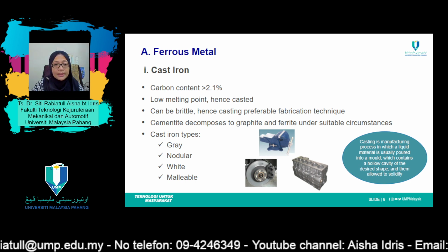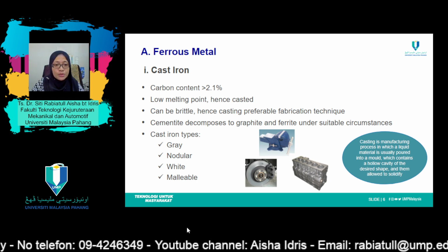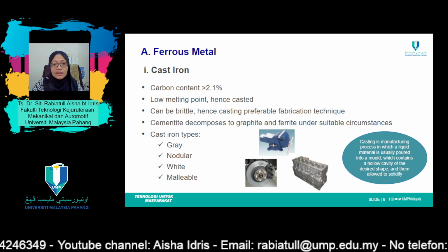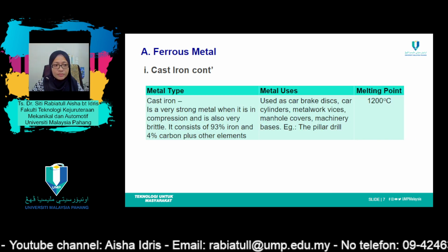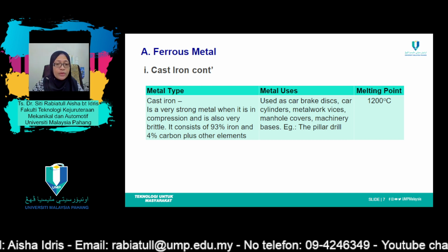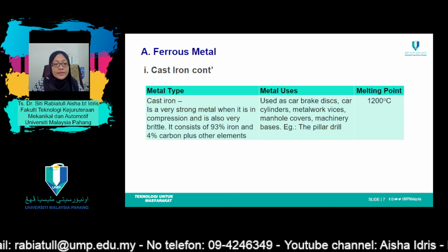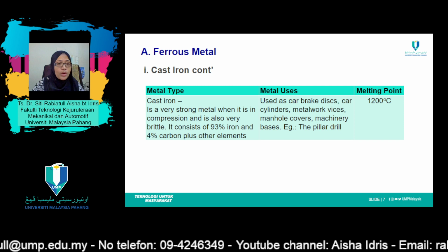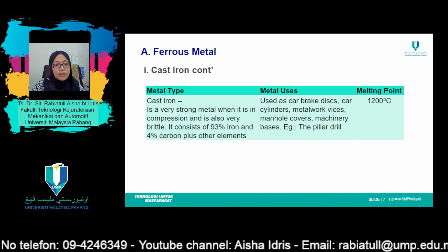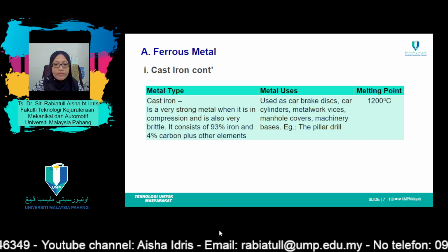And cementite is a metastable compound, and under some circumstances, it can be made to decompose to form alpha ferrite and graphite. The tendency to form graphite is actually regulated by the composition and rate of cooling. Graphite formation is promoted by the presence of silicon in concentrations greater than 1 weight%. Also, slower cooling rates during solidification favor graphitization, or the formation of graphite.